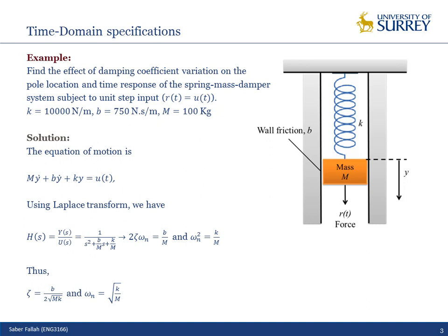If you look, both damping ratio and natural frequency of the system are functions of 3 parameters: damping coefficient, mass of the system, and stiffness of the spring. Correct? So if I want to achieve, for example, overshoot of 10% or settling time of less than 5 seconds, I can passively control omega n and zeta by changing the characteristics of the system.